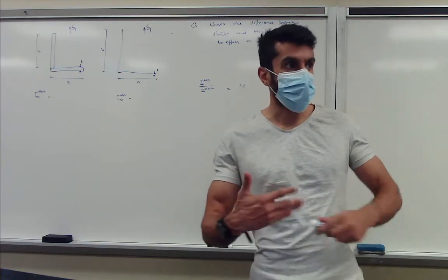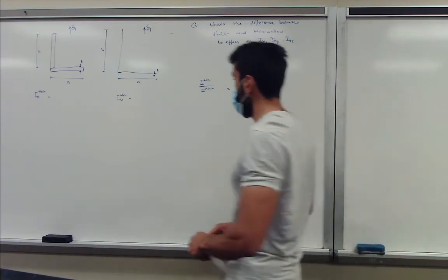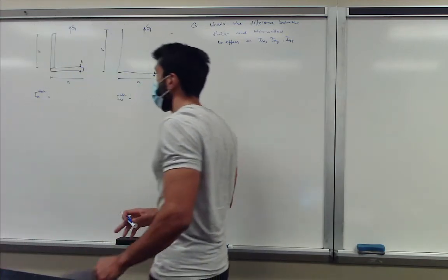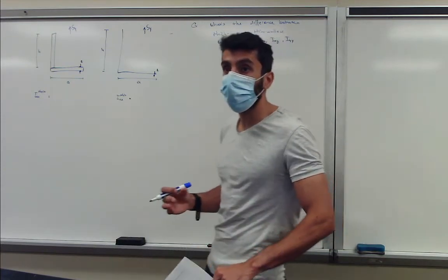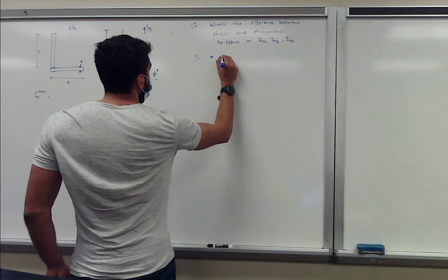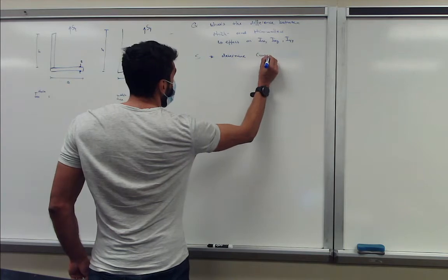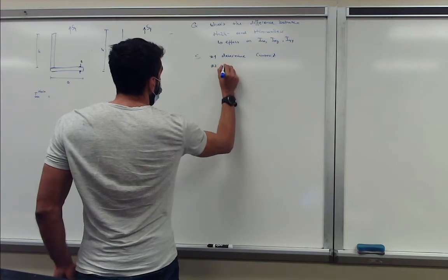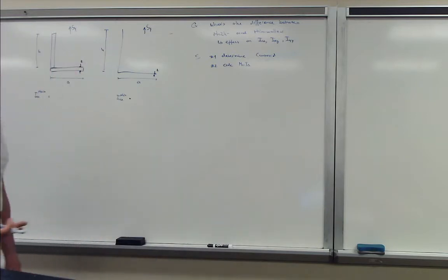Okay, I'm going to assume that you guys did a procedure at least, then we go through it ourselves. So basically the procedure for this problem is pretty straightforward. So we have an asymmetrical cross section. We cannot locate the centroid immediately, so we basically have to calculate it. So step one would be, it's called solution, determine centroid. And then step two is just calculate moment of inertia for both sections.